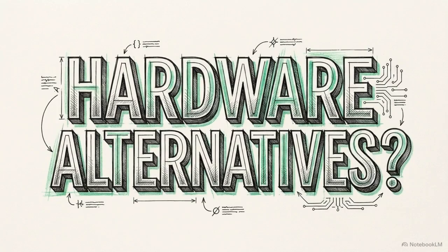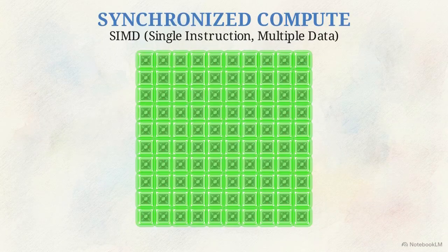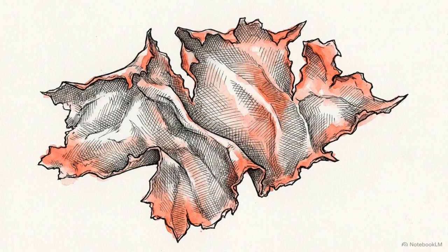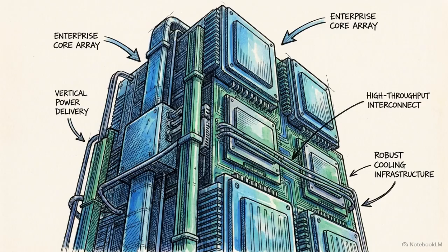Given this heavy reliance on parallel tracking, you might ask the logical hardware question: why not use GPUs, which offer thousands of parallel cores designed for geometric math? GPU architecture relies on SIMD processing. This makes GPUs highly efficient for uniform, predictable workloads. But crash physics are the exact opposite of uniform. Complex branching logic, erratic memory access, and continuous element deletion completely shatter GPU efficiency. The wildly unpredictable nature of spatial contact search mandates the flexibility of high-frequency, multi-core CPUs. They remain the core requirement for solving dynamic structural collisions.